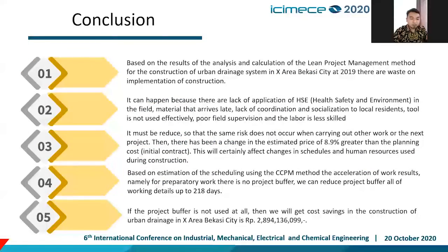For the conclusion, based on the result of the analysis and calculation of the CCPM project management method for the construction of urban drainage system in X area Bekasi city in 2019, there are delays in the implementation of the construction. It can happen because there is lack of application of HSA in the field, material that arrives late, lack of coordination and socialization to the local residents, the tool is not used effectively, poor field supervision, and the labor is less skilled.